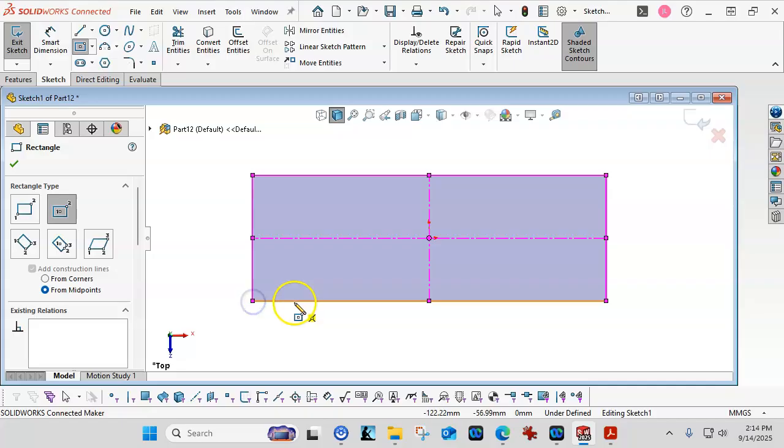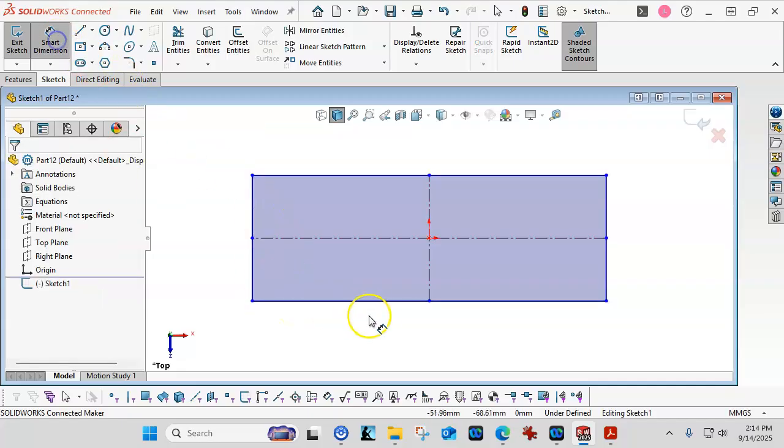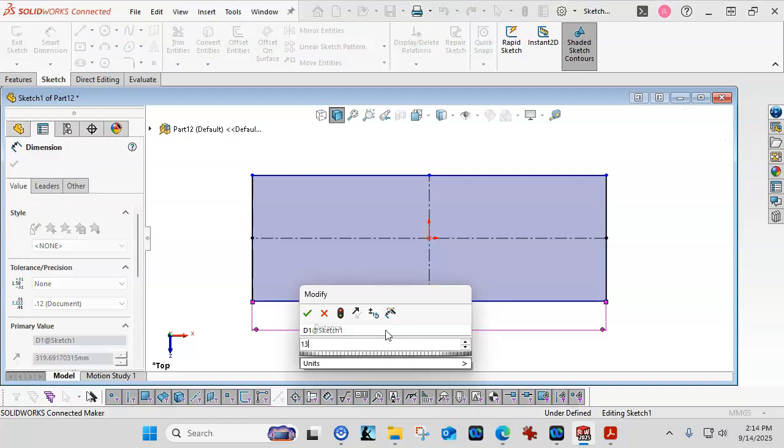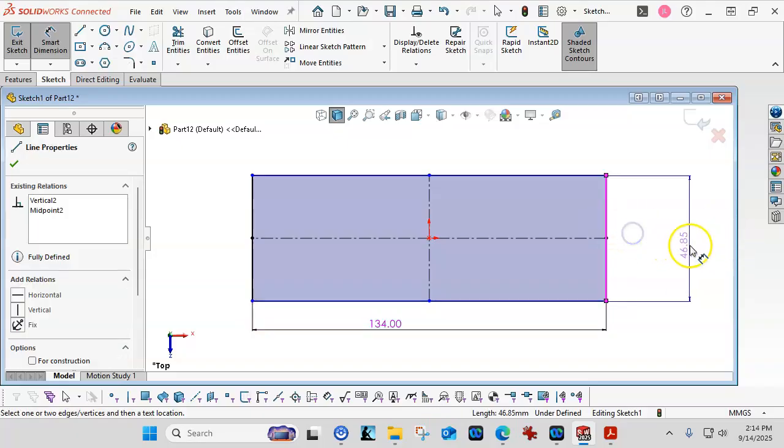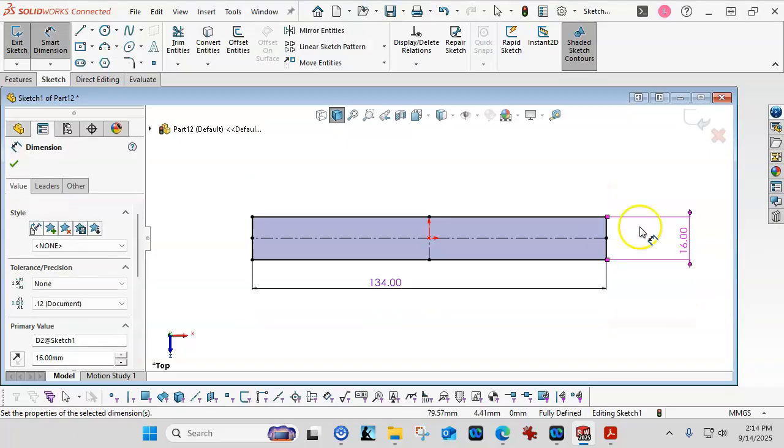If you drag straight out and not give it any depth, that is going to kind of choke on the information. So 164 between centers, and we had the diameter of 16, so that will also be the width.